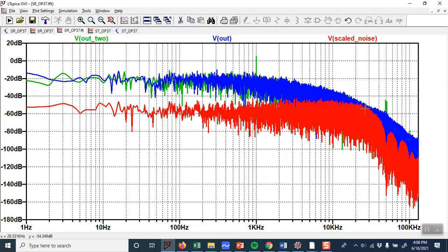So when you're working with noise, you need the standard deviation, the RMS of the voltage, right? But then you also need a measure of the frequency range that the noise is at as well. You need both really to be able to repeat anybody's work, and I've actually had a heck of a time doing that.